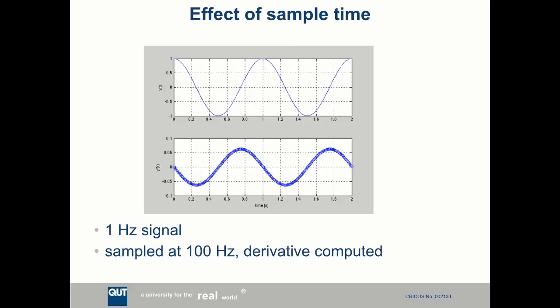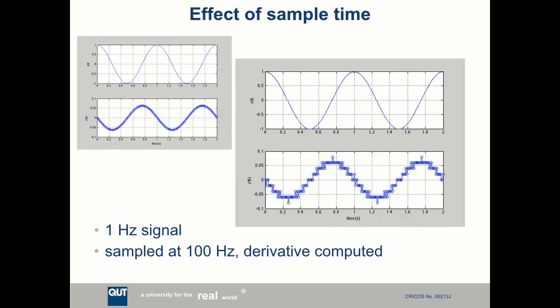And there you go. But if I quantize my signal first into just 100 levels, what's going to come out is a signal that looks like this. And it looks like rubbish, all right? So instead of the nice sine wave, what I've got is this thing that looks like a ziggurat or a pyramid or something like that. It's because I quantized the signal into 100 different levels.